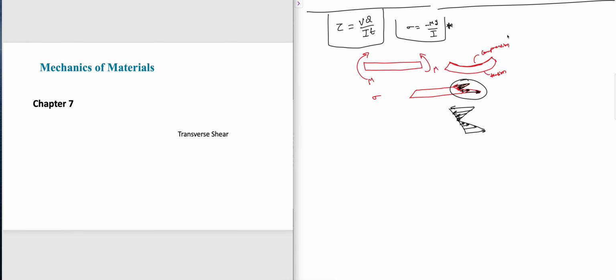So this is compressive stress acting on a small area dA, isn't it? Let's call it dA, acting on a small area. So this is a function of y. If we want to know the total force or the net force acting, we have to do sigma of y, which is a function of y, times dA, and we have to take an integral, and then we get the force.